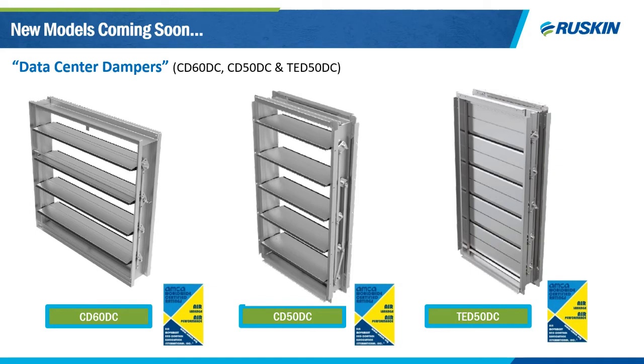So there actually is not a thermal pass from one side of the damper to the other when it's closed. For this reason, the TED50 DC is really best in cold temperature climates where the temperatures drop and you want to maintain that thermal break between your internal servers and the outside air. And so these models also have a new coupler option, which we'll discuss momentarily.